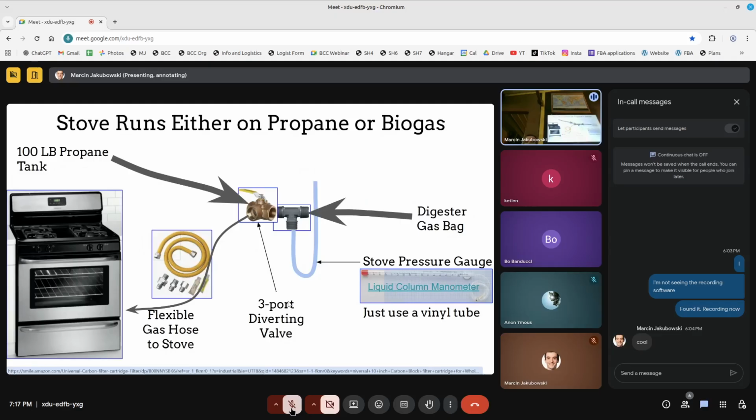We never got to the point of burning the gas, so we never followed up on that. But yes, you have to change the orifice sizes because of the way the flame burns differently. I don't think you'd be able to just use a valve and switch back and forth. You'd have to actually switch the nozzles. So maybe if you have 2 burners on natural gas and 2 burners on propane, then you've got it going. In this instance, I'd probably swap to a 100-pound propane tank with some form of natural gas.